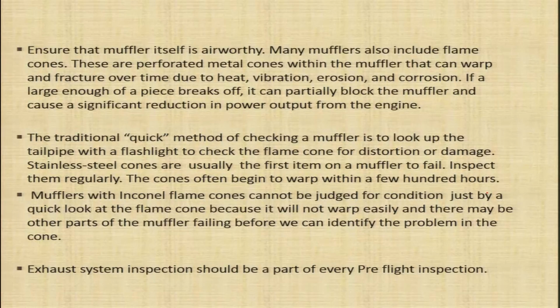In fact, the exhaust system inspection should be a part of every pre-flight inspection, and any observation, any leakage indication, should be taken very seriously, and we need to take appropriate action in an appropriate way as per the guidelines of the manufacturer in proper time. So the exhaust system should be thoroughly inspected for all the cracks, for all the vibrations, erosions, corrosions,